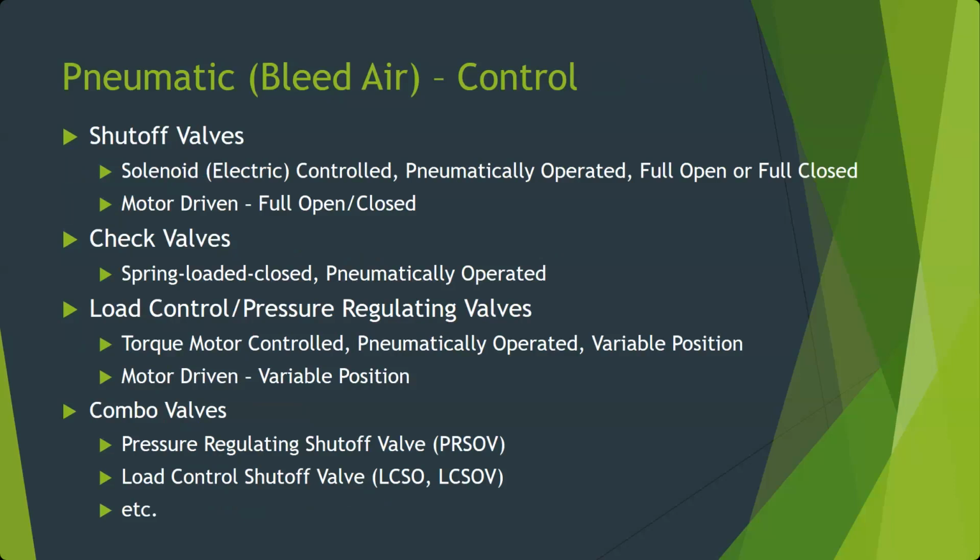Check valves, we've seen those, spring loaded closed, pneumatically operated. How are they pneumatically operated? Air just pushes on the valve, right? What style are most of these, you think? Think they're a butterfly valve or a poppet valve? They're mostly a poppet style valve. Air pushes on it, pushes a spring back, allows air to flow around it.